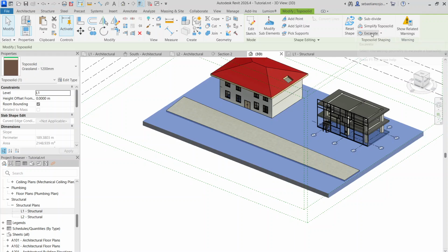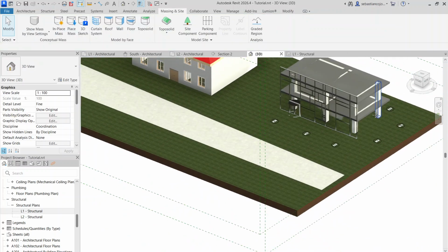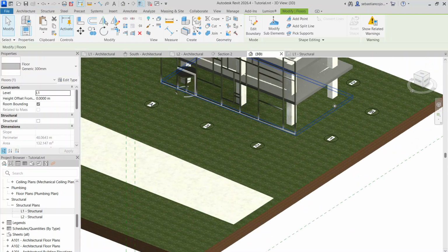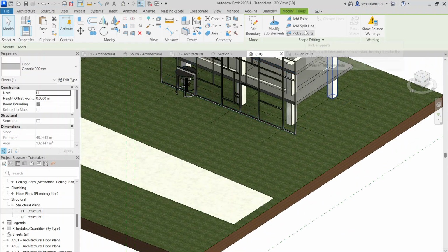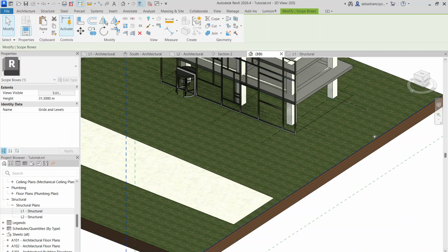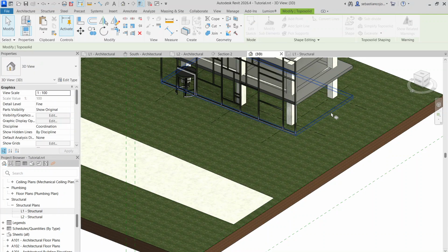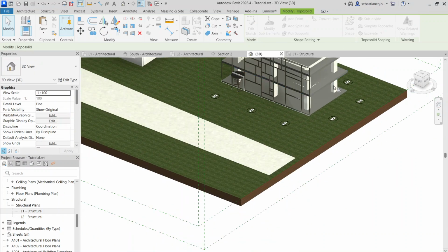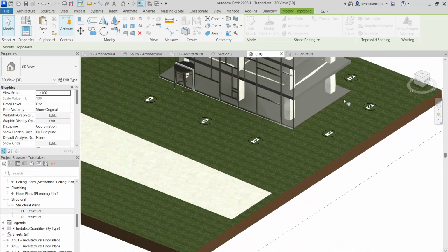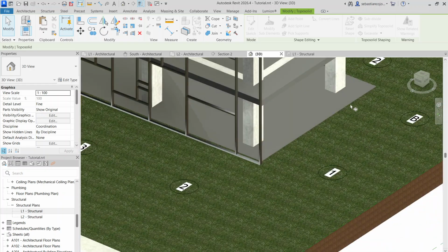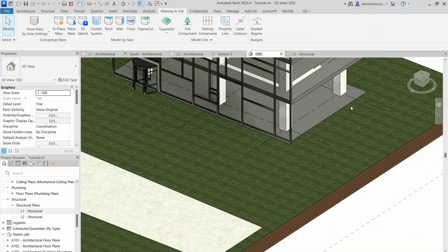And depending on what you have, I think I will try one thing. So I'll do, let's see, I should be able to excavate and select whatever thing intersects the Toposolid, for example this slab, and then excavate everything that is in that volume.